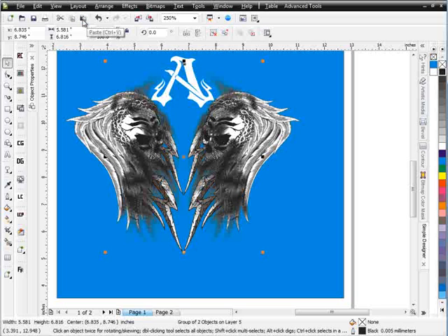because I want to darken that up quite a bit. Now I've got that set up. That's about as dark as I want it to be. I'm going to hold down Shift and Alt because I know there's 3 of these, and I'll select multiple objects. I've got the top one selected, holding down Shift and Alt, left click one time, 2 objects selected, one more time. You can see in the status bar 3 objects